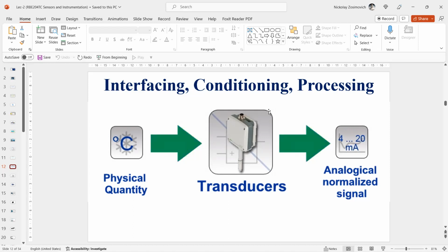This means that the converted electrical measurement signals are typically small and need additional conditioning such as amplification, offset reduction, and linearization. This can be achieved in many ways: by clever sensor design, by adding conditioning circuitry, or by processing the data in the digital domain. For processing data in the digital domain, it is necessary that data have been converted from the electrical domain into a digital representation, typically by analog to digital conversion.